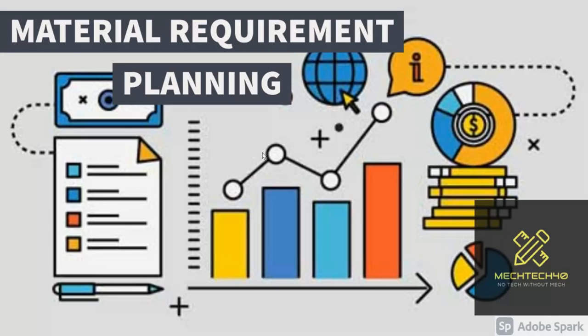If we go by theory, we can say that material requirement planning is the planning of the raw material, subcomponents, or parts required to manufacture or produce our component without any delay, or to meet the due date or the customer requirement. So that's why we are doing material requirement planning.